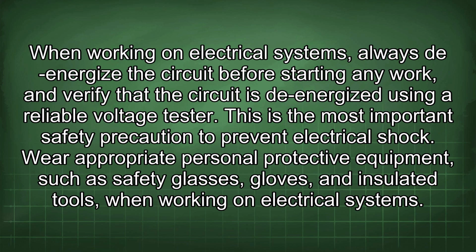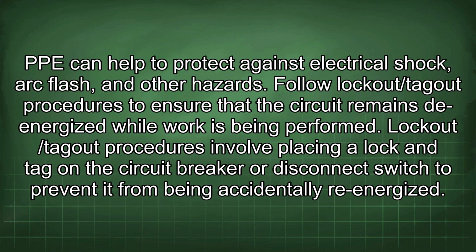Wear appropriate personal protective equipment, such as safety glasses, gloves, and insulated tools, when working on electrical systems. PPE can help to protect against electrical shock, arc flash, and other hazards.